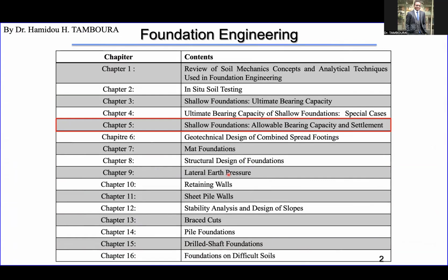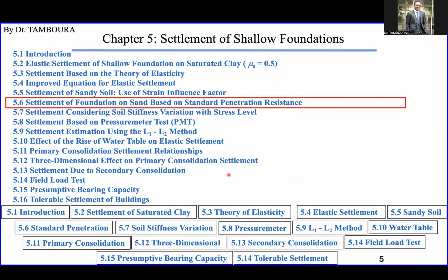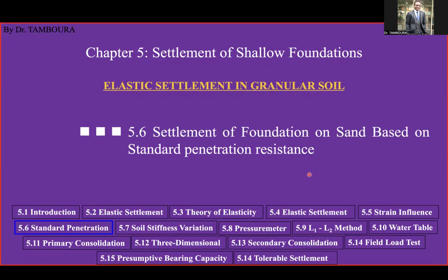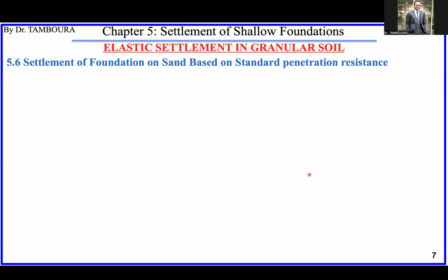Shallow foundation, estimation of settlement. Today we are going to look at how to estimate settlement based on the standard penetration test or standard penetration resistance. If you do SPT, how can you get the amount of settlement of your shallow foundation from the SPT N value? For those who don't know what SPT is, please go back and see chapter number 2 of this program. So let's go. SPT, standard penetration test.